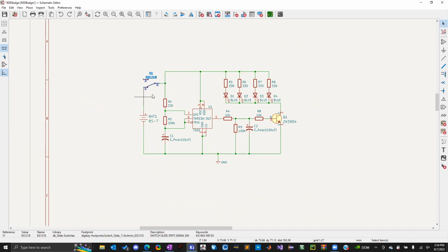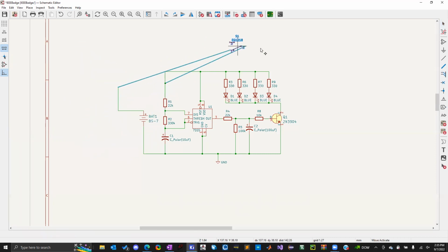You can grab the wire and then click move, and that will just move the wire, compared to if you click the wire and try to drag it like this, it will extend the wire. So I guess maybe you'll have to move the wire around first, and then you can slide the component to extend the wire like that. But if you just try and move the component with the connections, you'll get this weird ugliness.